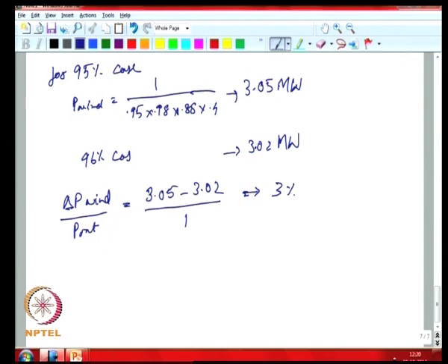So, the amount of stresses in the blades etc. can be reduced, and because your power converter is now sitting at the end of a chain right next to the point of common coupling, it forms a crucial link in the overall system, and there can be significant upstream benefits. Even though your cost of the power converter is only 10%, it can have implications on the balance of plant, which is 90% of the cost.